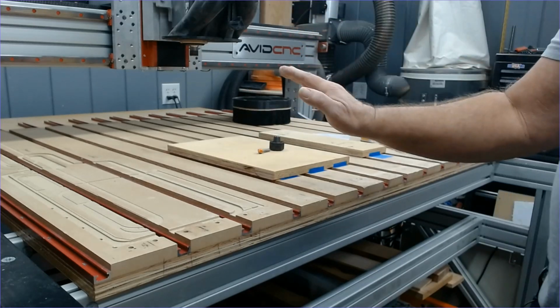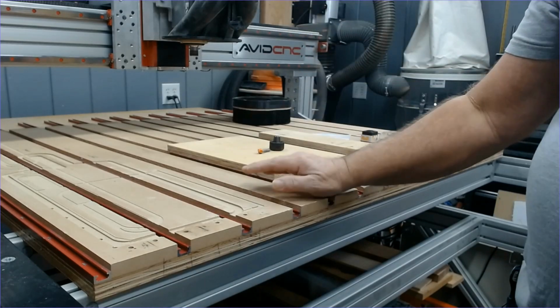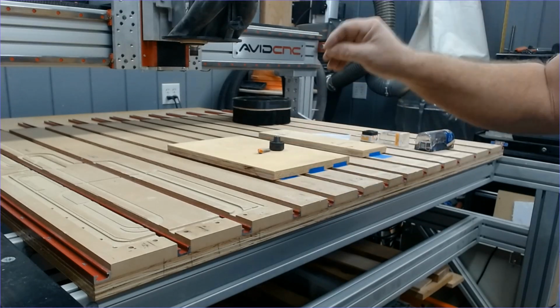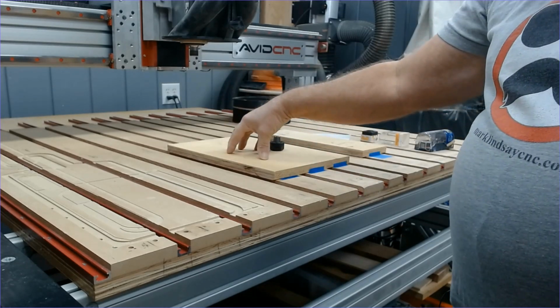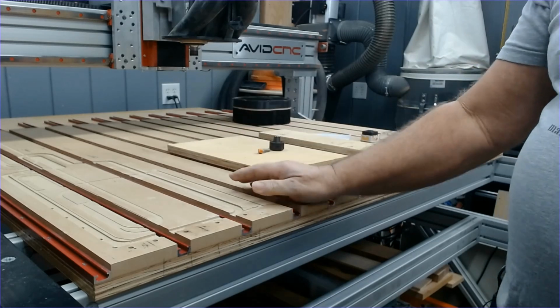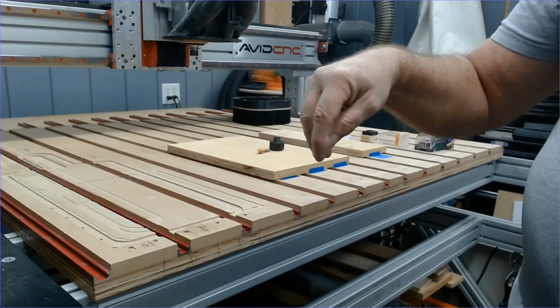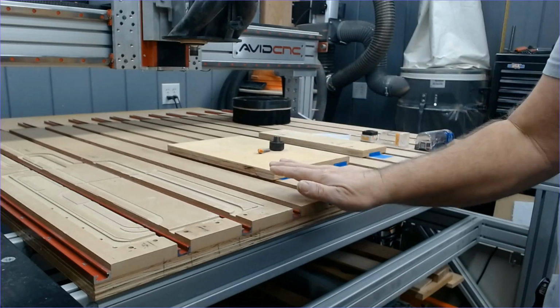You will very rarely work in machine coordinates. In the few years that I have been working on CNC routers, I have used machine coordinates only a handful of times. 999 times out of 1,000, you will be working in work coordinates. It's important that you understand the distinction between machine coordinates and work coordinates, however, because that's how you create work offsets and fixture offsets, is using those machine coordinates.